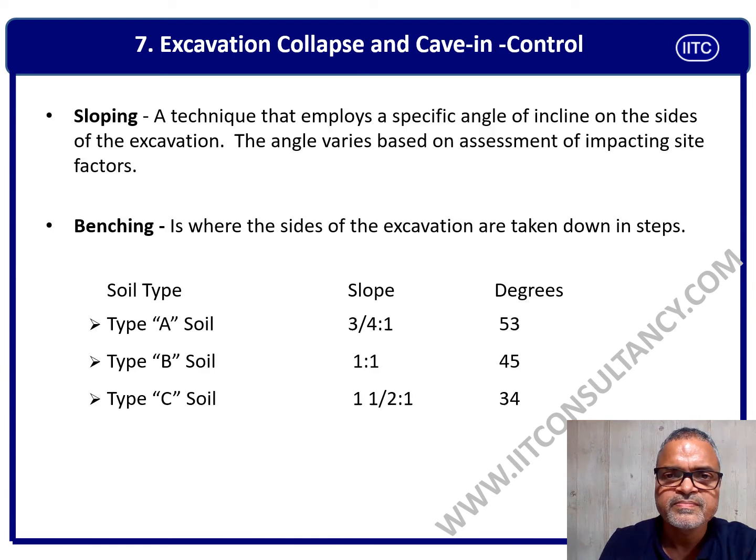Guys, an important safety measure is sloping. Sloping is a technique that employs a specific angle of inclination on the side of the excavation. The angle of the slope may vary from soil to soil, and with the size of the excavation.